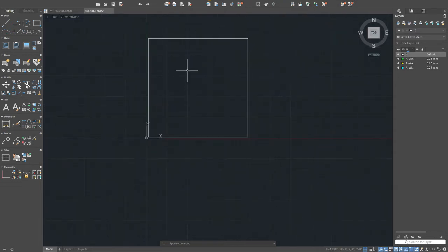So you may ask, where is my layer? When am I going to use it? Don't worry about it. Every time you draw something on the 0 layer or any layer, you can select it and then switch the layer, and automatically the object will adopt it.